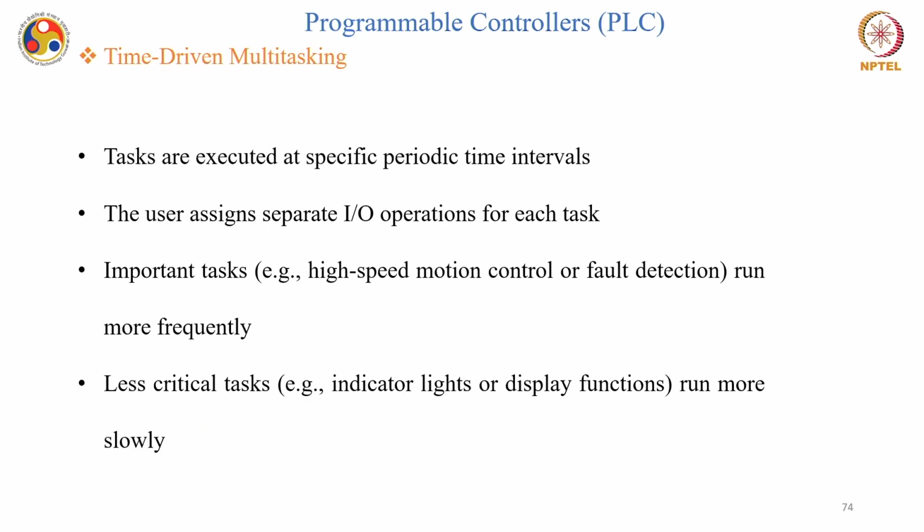Let's understand what I mean by time driven multitasking. Here the tasks are executed at specific periodic time intervals. The user assigns separate input output operations for each task. Important tasks, for example high speed motion control or a fault detection which has to be done immediately, run more frequently, and less critical tasks like indicator lights or display functions run more slowly on the system.